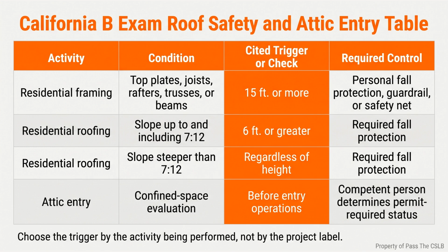I also verify that access is usable, that mechanical equipment can be removed, that fall protection matches the activity, and that a competent person has evaluated attic entry hazards. Those are separate checks, but they all meet at the same general contractor responsibility, which is coordinating work before hidden conditions become defects or safety problems.